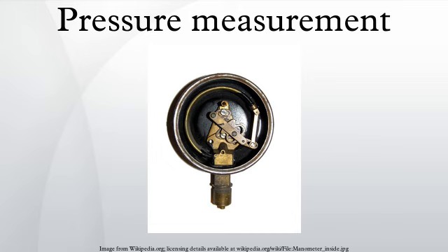The most common ion gauge is the hot cathode Bayard-Alpert gauge, with a small ion collector inside the grid. A glass envelope with an opening to the vacuum comes around the electrodes, but usually the nude gauge is inserted in the vacuum chamber directly, the pins being fed through a ceramic plate in the wall of the chamber. Hot cathode gauges can be damaged or lose their calibration if they are exposed to atmospheric pressure or even low vacuum while hot. The measurements of a hot cathode ionization gauge are always logarithmic.